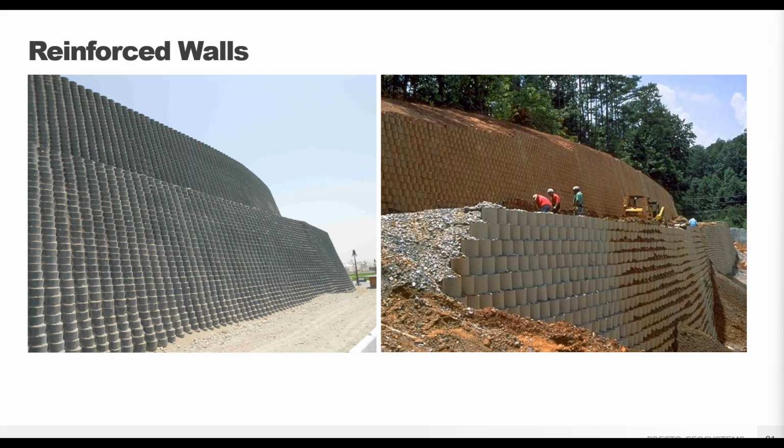So a 6-meter or 20-foot high wall needs about 4¼ meters or 14 feet of reinforcement grid. And a 40-foot high wall would need about 28 feet of reinforcement. You get the idea. So using shorter tiers or terraces allows you to keep the reinforcement length reasonable while still achieving the overall required height.